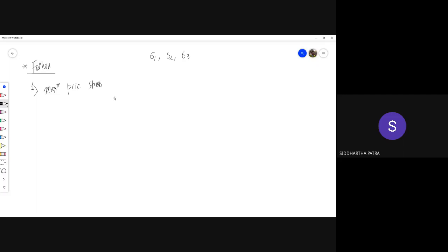Typically in brittle materials, this type of behavior is seen. So if I were to plot them in 2D, let's say there is sigma 1 and sigma 2. Now this plane right here is one of the principal planes, the plane that is normal to n3, the third principal direction. And by plotting everything in sigma 1 sigma 2, this also means that sigma 3 is 0. That's why we don't need that coordinate. So that's just an assumption.